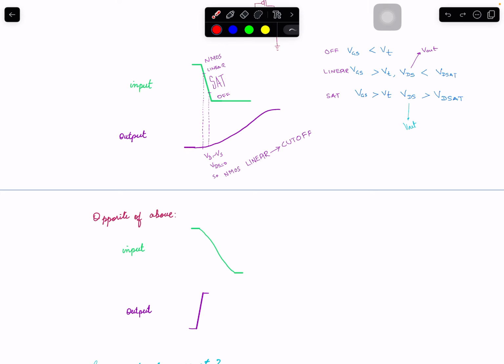That's why, as you will see in physical design, there is a limit on max transition time, and we try to keep transition time within certain limits. Sometimes it's not a good idea to have some nodes that are extremely fast and others slow. A slow input can come in and create a fast output, and if there is a high drive strength, then we can have higher power. So it's better to be consistent, with identical input and output transition times within a certain range.